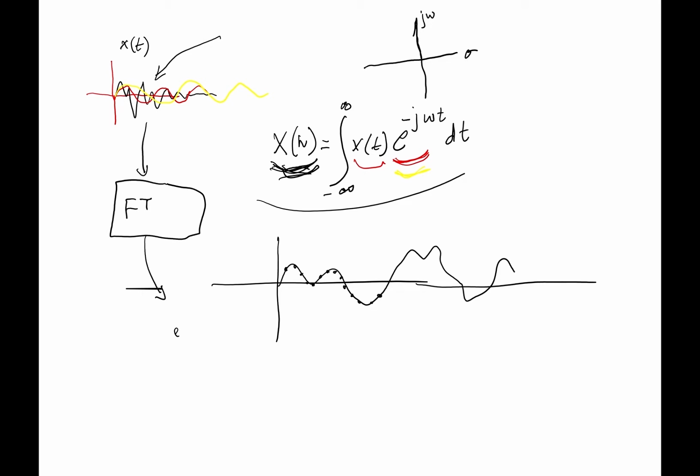It depends on your signal. Then if they want to know if 100 hertz is present in this signal, they multiply by a 100 hertz sinusoid, but it's also only samples of this 100 hertz sinusoid. Now instead of the integral and this multiplication, they multiply sample by sample: this sample by this, and this sample by this, and so forth. Integration becomes a summation. Then they sum the product of corresponding samples, and the value will tell you how big this frequency is.